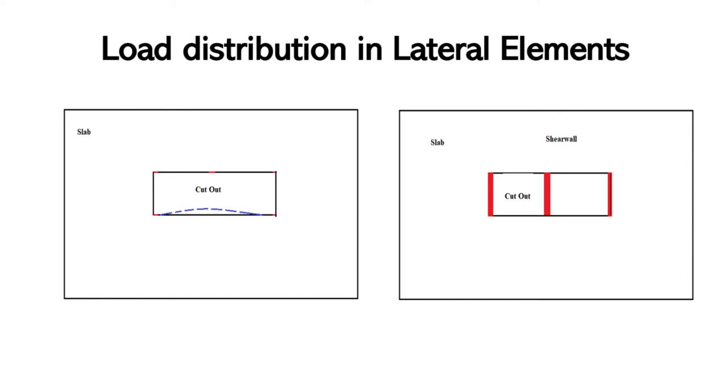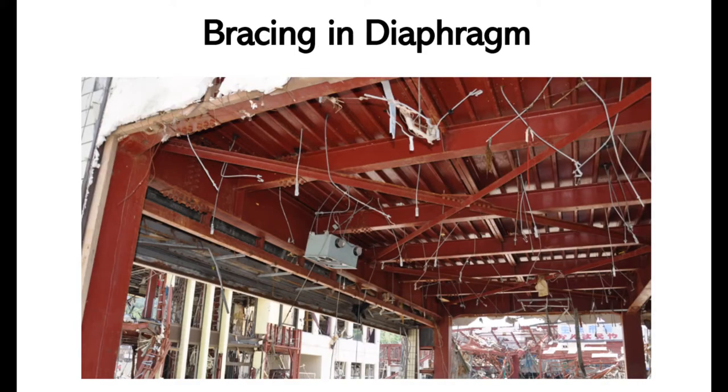In the case of a semi-rigid diaphragm, a semi-rigid diaphragm is nothing but a real analysis of the plate element after it has been generated with the plate mesh. So it would capture the actual structural response, and these internal elements like the shear wall would be calculated with the actual stress that they are supposed to experience.